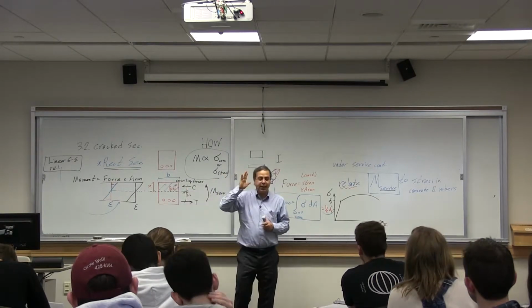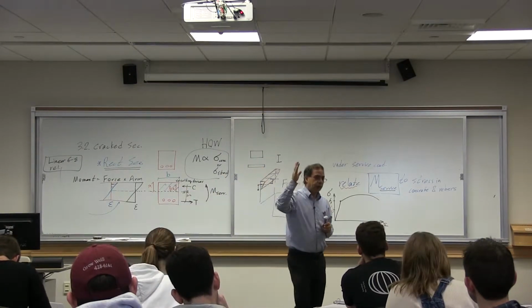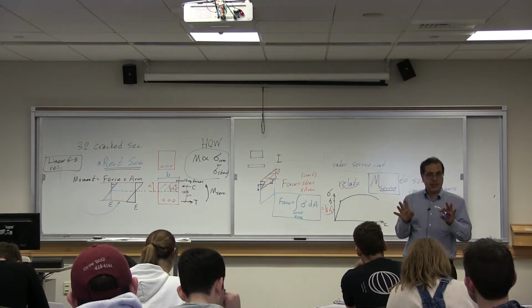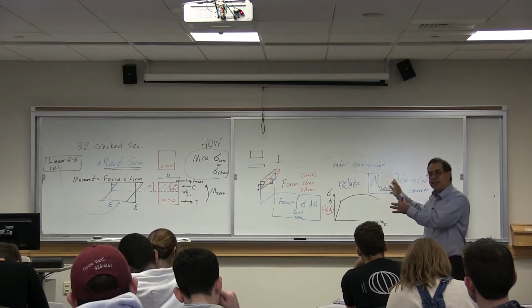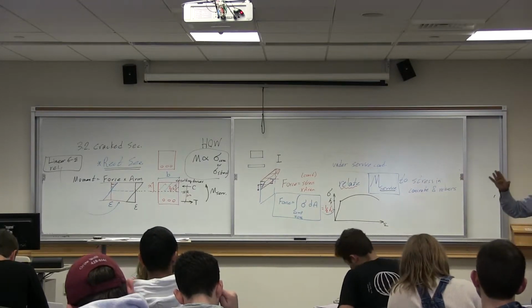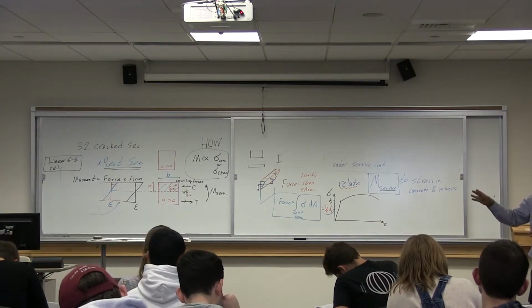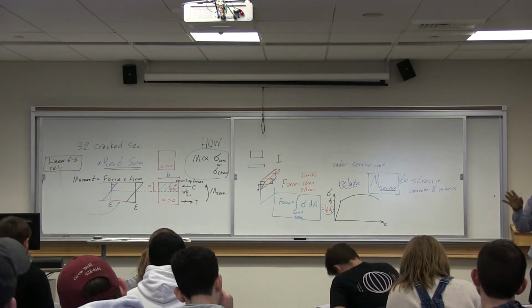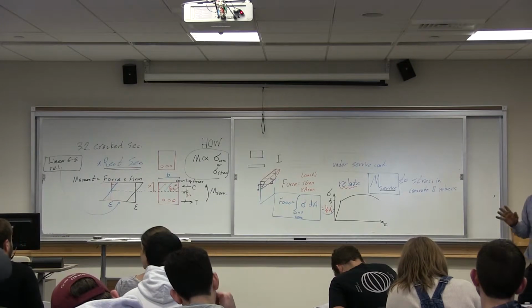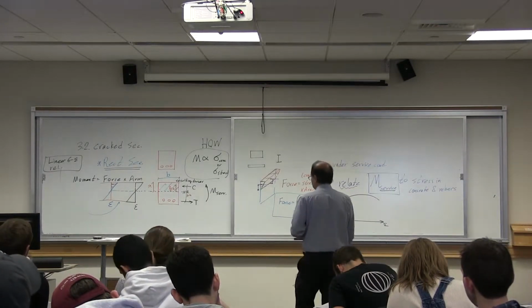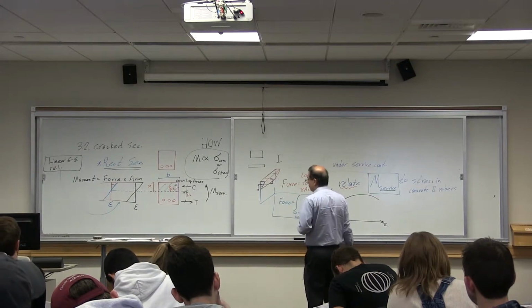Please do not think that compressive force is always applied at 2/3 of the height. That is not the case. In this case, having all the assumptions that we had, primarily the fact that concrete and steel remain linear. Otherwise, in general, it is not at 2/3 of the height. We will look at other cases later on, maybe today or tomorrow.